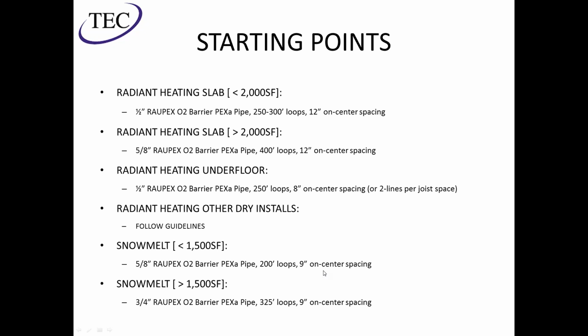And then each of the manufacturers will have a table. You'll be able to go in and say, all right, I have half-inch pipe, I have 1 GPM, and here's my head loss. So it's all about limiting your head loss to an acceptable factor. Obviously, the lower you keep it, the cheaper the pump that you can use. So there's obviously some balance there.